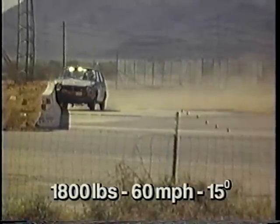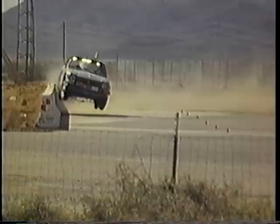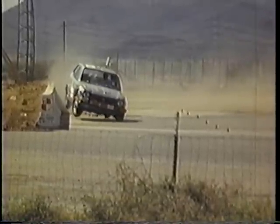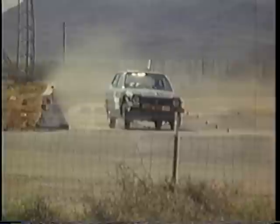The shaped profile of this bridge rail causes a vehicle to ride up the barrier as it is redirected. This vertical motion dissipates energy, resulting in less vehicle damage and better occupant response than the comparable impact with the vertical wall. This test showed that the occupant responses were within the allowable range.